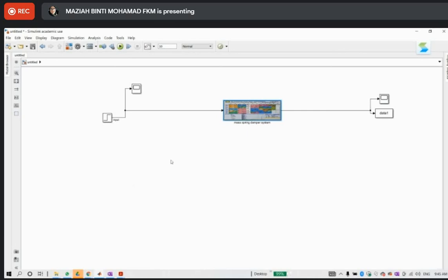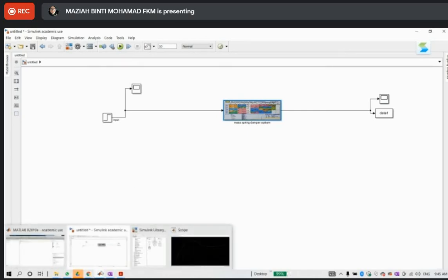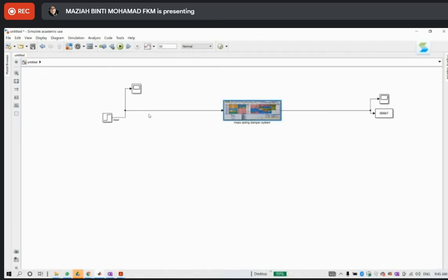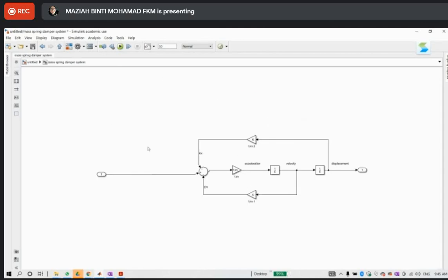Okay, so you will be able to do similarly as before: you draw a PID controller, then you tune the PID, auto tune the PID to see the response of the system, right? So basically, this is how we draw a dynamic system, because you might not know about this 1/s here in order to get velocity and displacement.